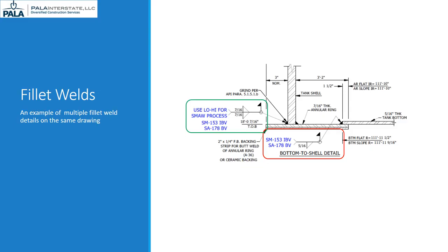The weld detail outlined in green is a corner weld. It is also a field weld that goes all the way around the tank. This one is 7/16 of an inch and welded on both sides of the joint. It also gives specifications in the tail. This picture is a perfect example of how much information can be conveyed efficiently with these symbols, as opposed to writing all the required information out. Now let's look at stitch welds, because they are typically fillet welds as well.